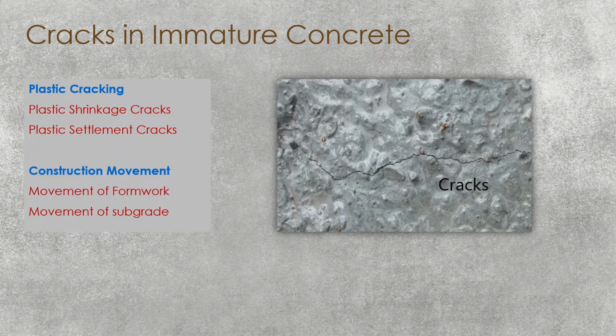So part of the area may be loaded heavily and move towards the other end during concrete pouring. That also could be a reason for cracking, due to differential movement of the subgrade. Therefore, we have to be careful, especially in foundation construction, that the ground or soil on which the foundation rests has minimum settlement.